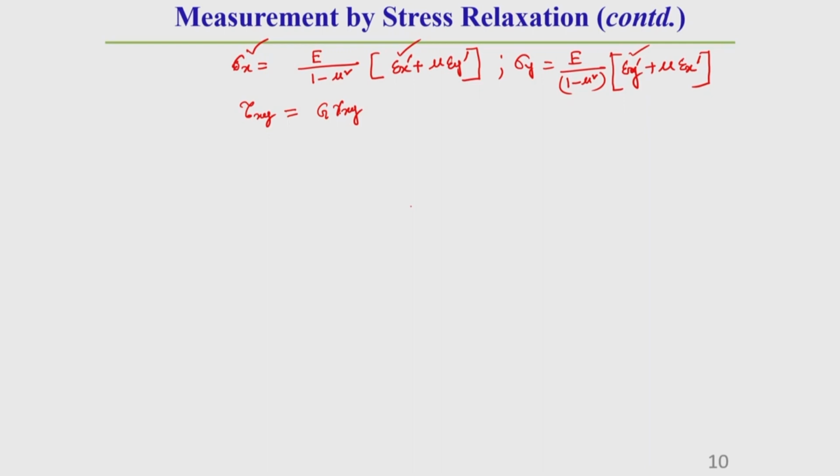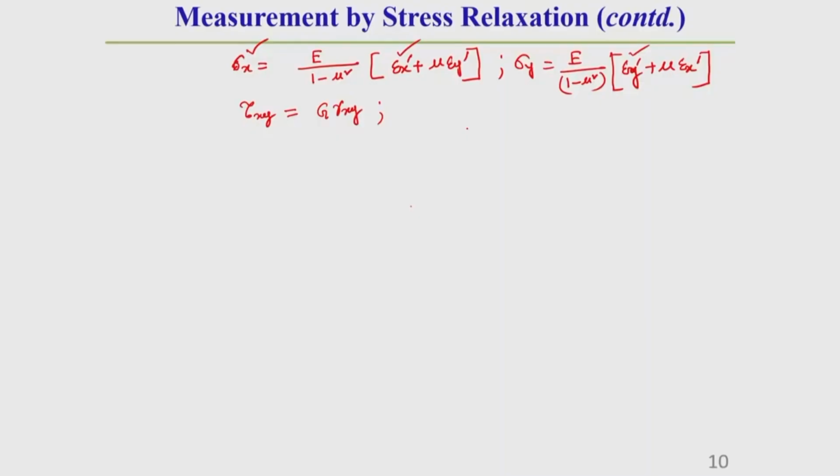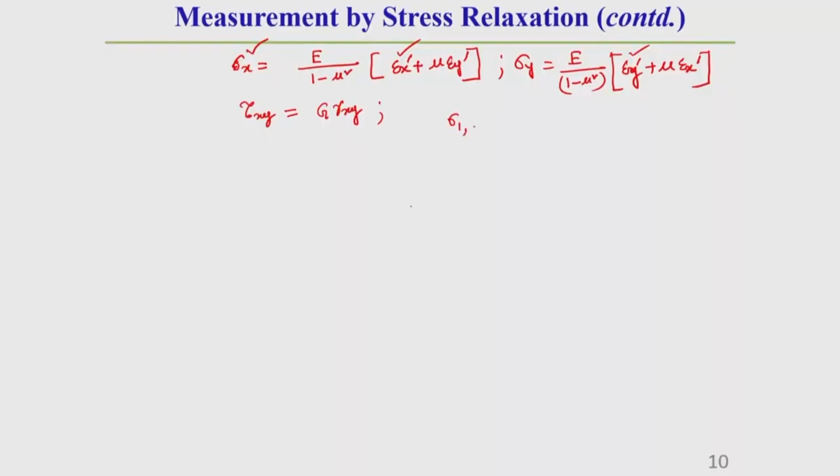So, once you know all these things, you can easily find out the maximum stress developed in that welded structure, or in that structure which is subjected to some residual stress, and what its direction is. How can you find this out? If you know sigma x and sigma y, there is a relationship between sigma x and sigma y and the principal stress. That is very well known to you. I am not going into detail.